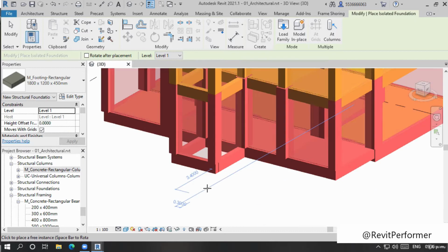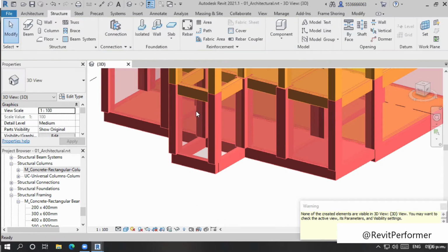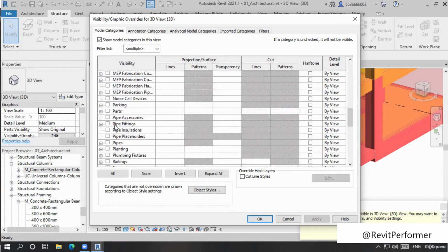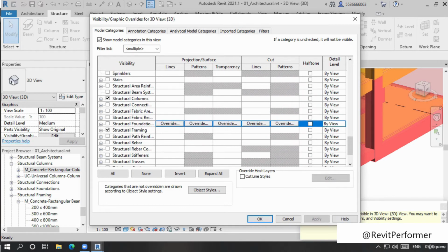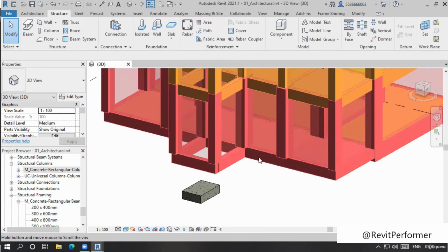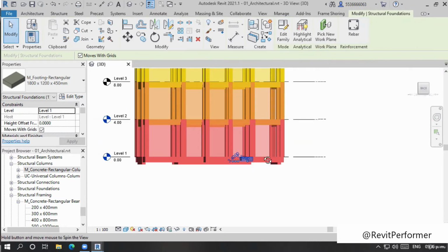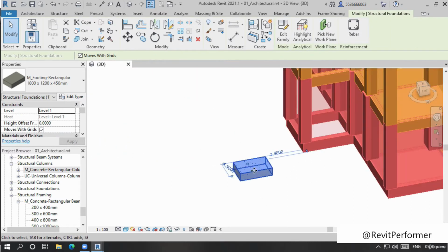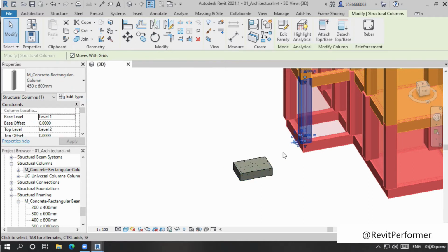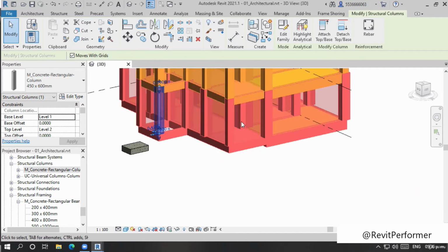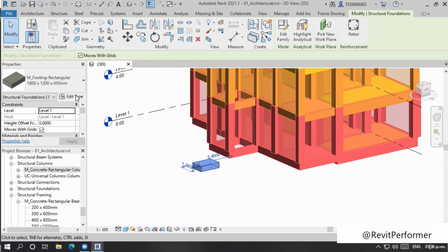We need to change it because that's just gonna be the basic element, Foundation. That's just the generic foundation. But we want to have a mixed type of element. So the biggest ones we have are the little ones, these ones, 1,200. So I'm gonna duplicate the family.